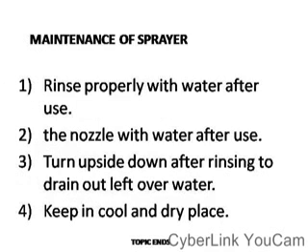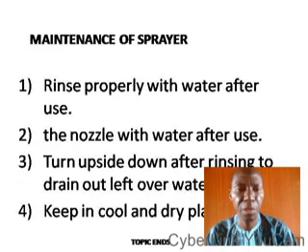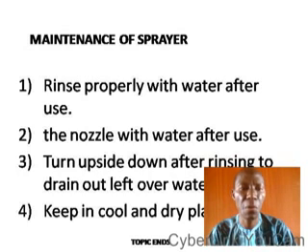Maintenance of sprayer. 1. Rinse properly with water after use. Immediately after using any sprayer, it must be rinsed in order to remove the leftover chemical solution. 2. Rinse the nozzle with water after use.